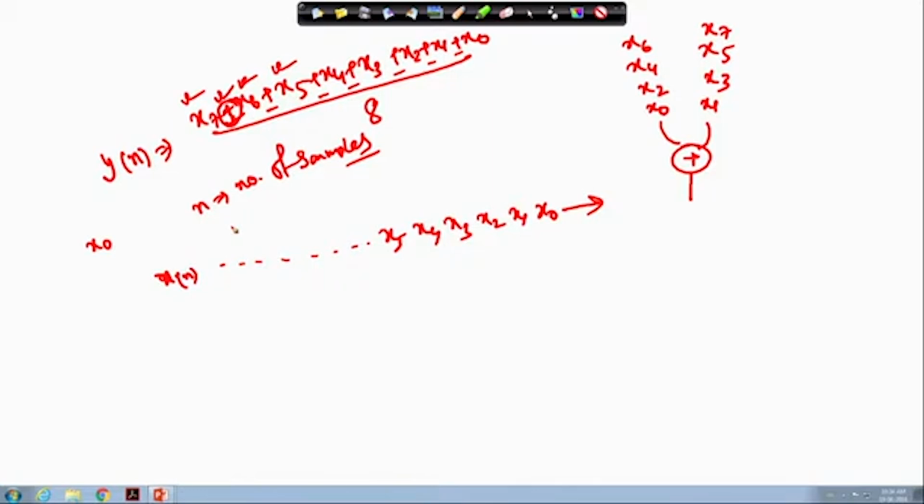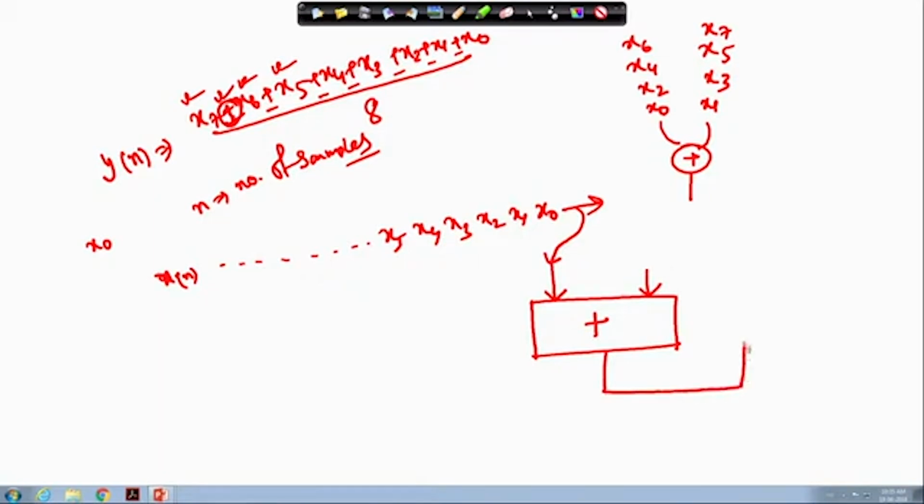So, that architecture is basically nothing but the serial operation. Now what is needed is one addition operation, where one input comes from the incoming samples, and the other input to this adder comes from the register. That is the sum, which is again fed back to this block.